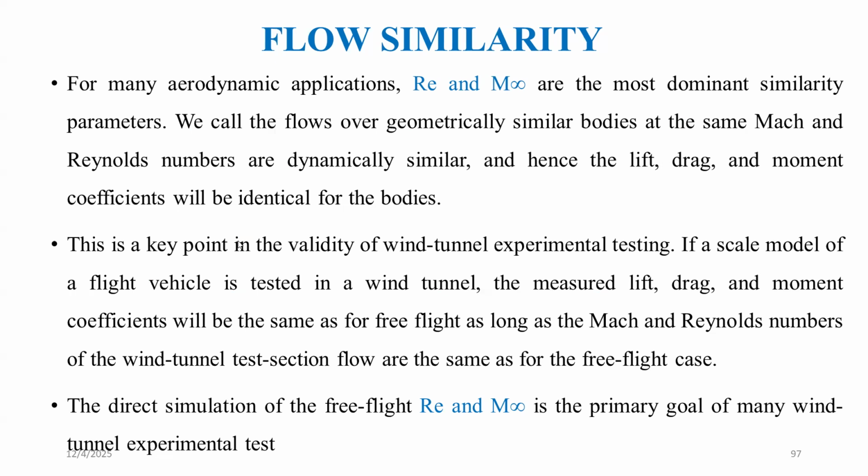This is the main point in which we are validating the wind tunnel experiment testing with our real application. If a scale model of a flight vehicle is tested in a wind tunnel, the measured lift, drag, and moment coefficients will be the same as for free flight, as long as the Mach number and Reynolds number are the same as in the wind tunnel test section flow.